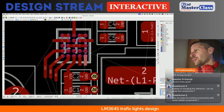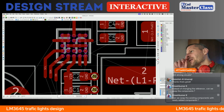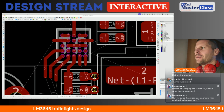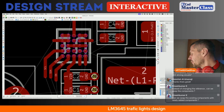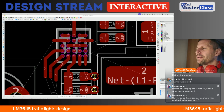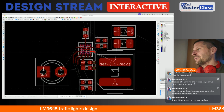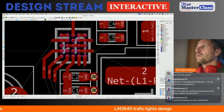I will use the tracks instead of the polygon near the pads, because for my manufacturing, my experience is that when there is a polygon near the pads, it can cause shorts on the pads. But where there are two tracks with the mask in between, it avoids creating shorts. But I don't know. Okay.